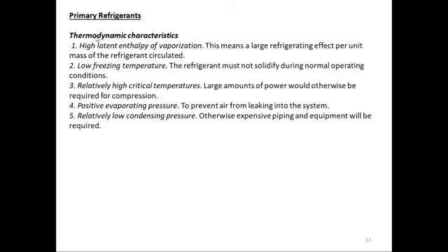The primary refrigerant's thermodynamic characteristics: it should have a high latent enthalpy of vaporization, because we want to utilize the latent heat of vaporization, so it can absorb much of the heat from the system and expel it to the outside. This means a larger refrigerating effect per unit mass of refrigerant circulated can be achieved if it has higher latent enthalpy of vaporization. Low freezing temperature: the refrigerant must not solidify during normal operating conditions.